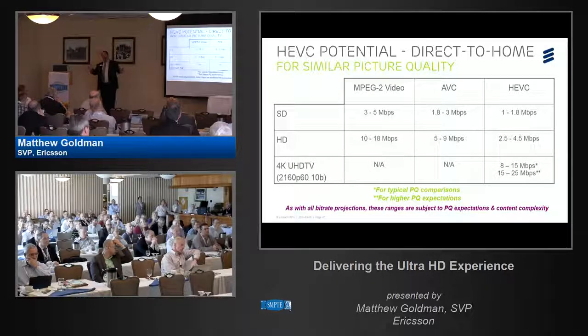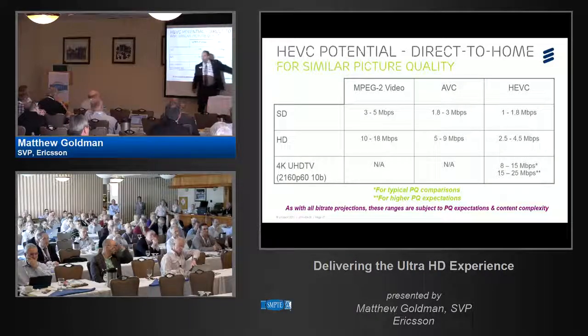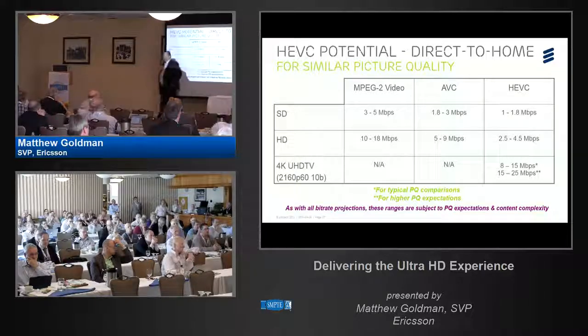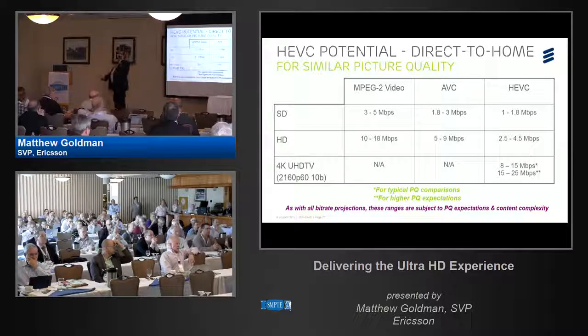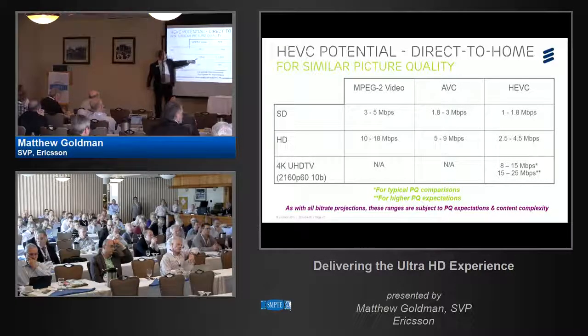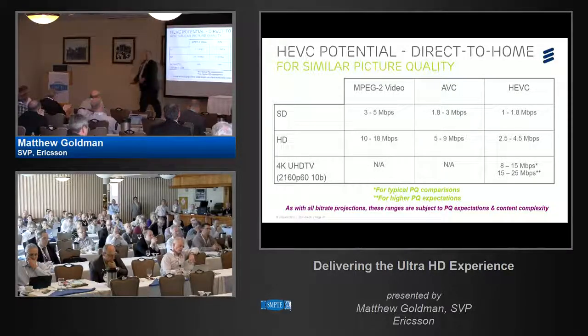But again, they're picking it now with today's encoders. I guess I should thank you, Hugo. These are mature encoder bit rates. So Korea has now selected 30 and 40 megabits per second, but that's using today's encoders. We know encoders get more efficient. Just like I said before, the same standard 20 years ago with technology needed about 18 megabits per second. Now it's probably about 12. I know I said 10 here, but it's probably more like 12.